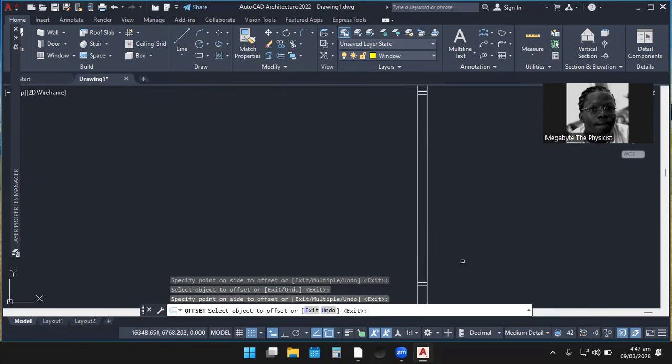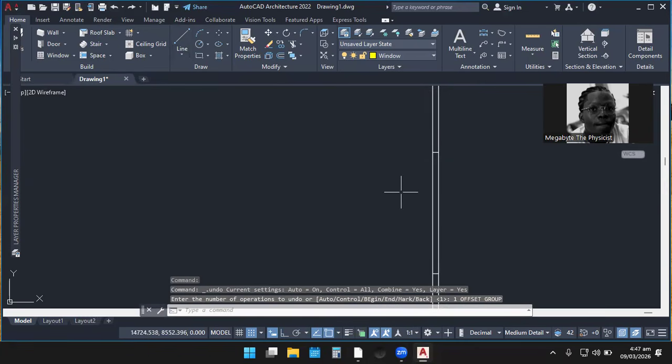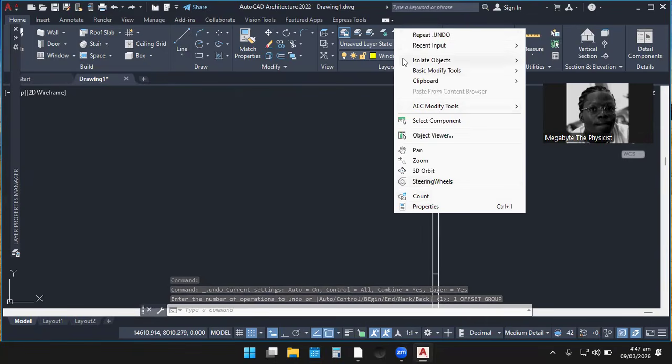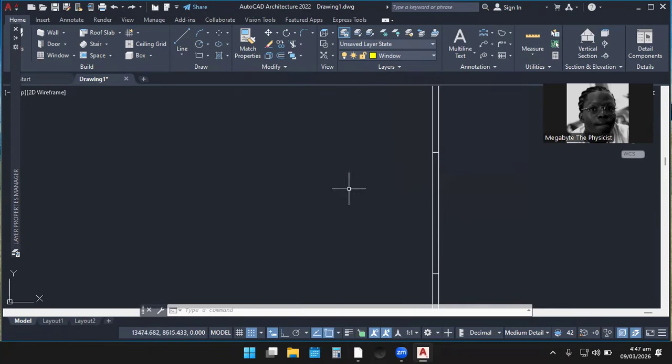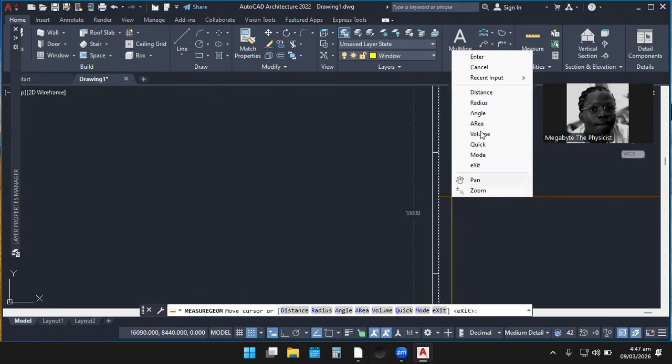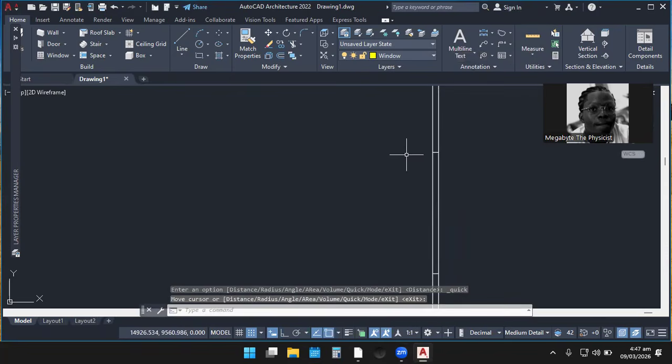Okay. But even before our wall thickness, even before the thickness of our door, let's quickly find the division for these doors. Okay, so let's remove this command. So the full length of this is 3233.333. Okay, so let's just remove it. After removing this, I divided this into three. I had 1077.777. So let's quickly offset.